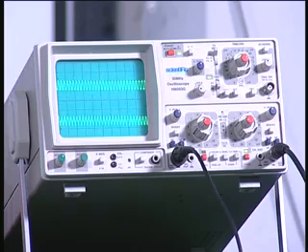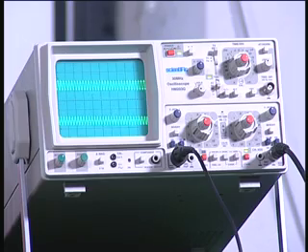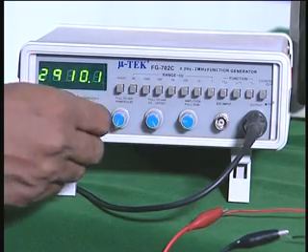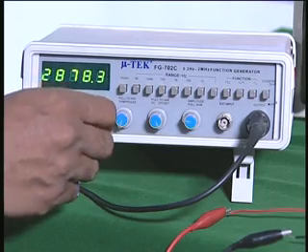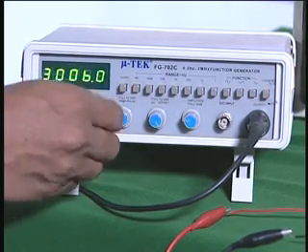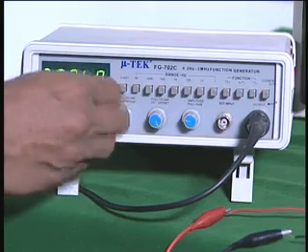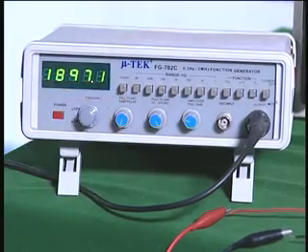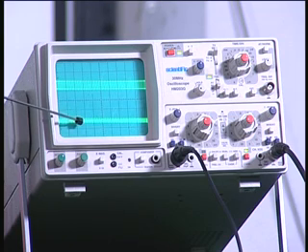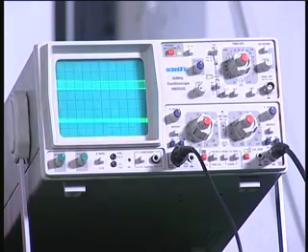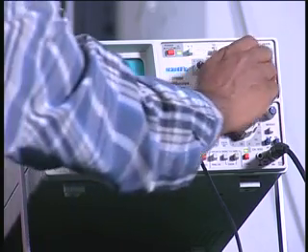So if I now go to higher frequency like 1 megahertz, you can see the output has almost decreased in amplitude. So when this decrease starts is what we should worry about. Around 200 you would find the output is already less compared to the input, less than what you had previously, because the gain is 1 but they must have the same amplitude in principle.